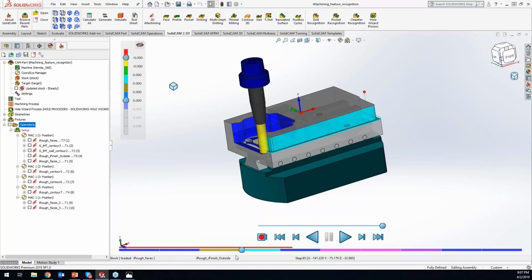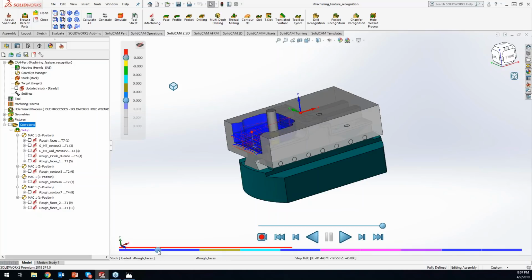These colors are showing up for you guys down here. So if I want to get to where a tool change is, you can see that this one, tool number 7, doesn't have a holder, but as soon as I get to the new blue section here, it brings in my new tool with the tool holder. Get over to the yellow, we're switching over.